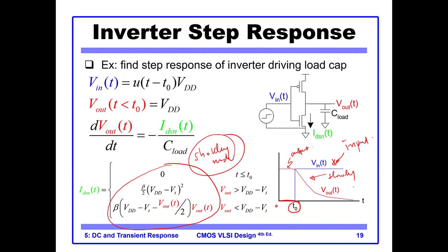And this is a very important characteristic that determines our delay. So if you look carefully, basically this kind of curve you have studied in circuits for the capacitors. This is the RC discharge of a capacitor.